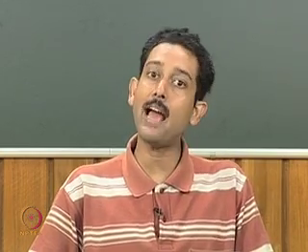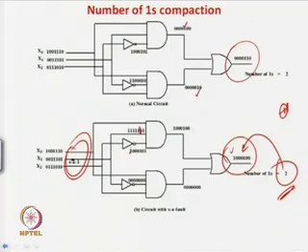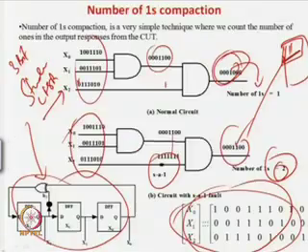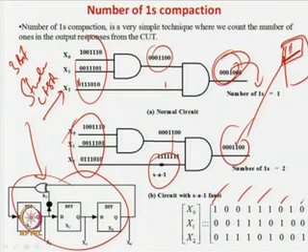But again, for a compaction technique you have used, the subset of test patterns you are using for this pattern generation may have a very high aliasing effect. That means you have taken a compaction scheme, and that compaction scheme is determining which test patterns you have to apply. For example, you select a compaction technique which is very good, the area is less, and you get very little aliasing, but the test patterns to be used are this one, this one, this one, this one and this one, all alternate.